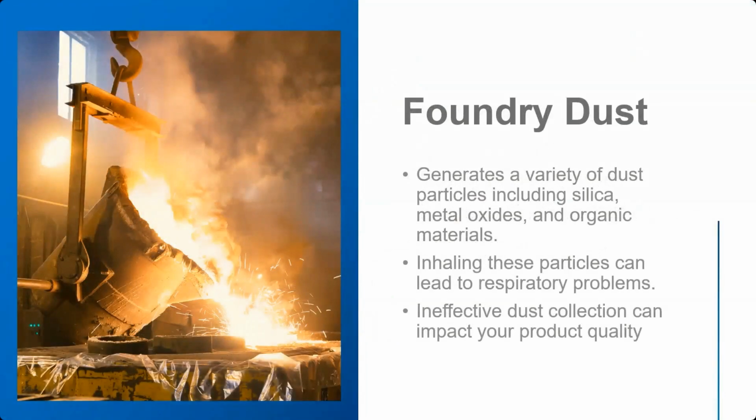So what is Foundry dust? Primarily, Foundry dust is going to be sand and silica. There's going to be metal oxides, some organic materials used in the binding, and a lot of these are really dangerous if inhaled, and they can lead to a lot of respiratory problems. So I think one of the biggest focuses today is just keeping the workers safe. And of course, ineffective dust collection can also lead to some product issues in the end.